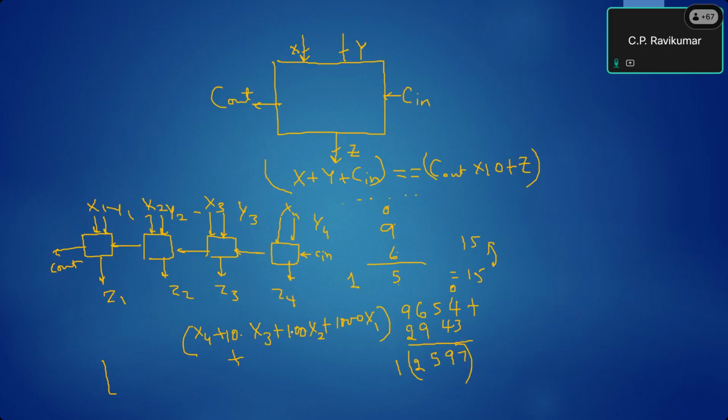So it's better to write a property. And if it is a formal verification tool, it will try to prove that this property is always true, it doesn't matter what test case. Either it will prove that it is true, or it will give you a counter example and say it cannot be true because there is one example where it is not.